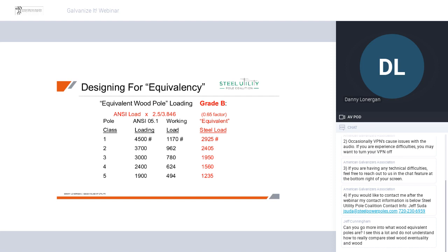So if you as a user, as a designer, have made the decision to be in grade C, you just need to understand you have to pick the correct pre-designed pole to support the load that it may see. So it's not a one-to-one equation, is the takeaway, and it typically sizes up. So if you're in a space of grade C, a quote unquote class 1 pole would size up at a minimum 1 class. So a class 1 would be an H1, a class 2 would be a class 1. So again, that is a pretty understood conversion and side by side.